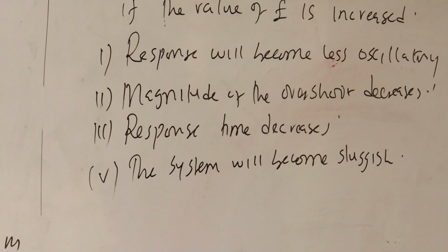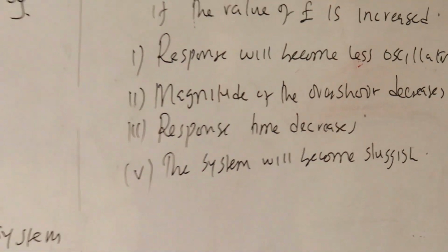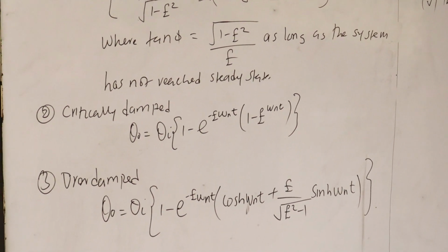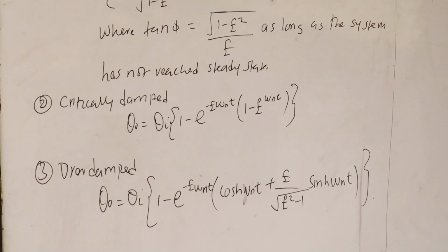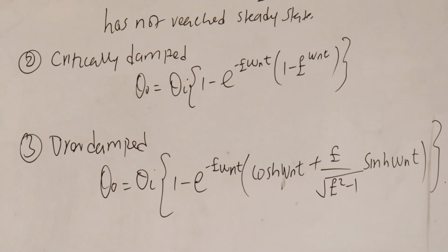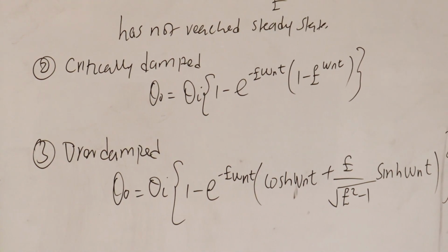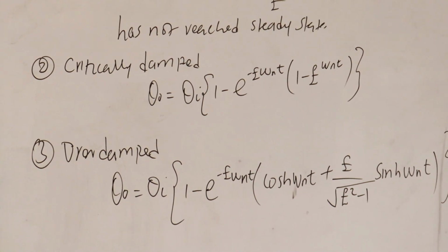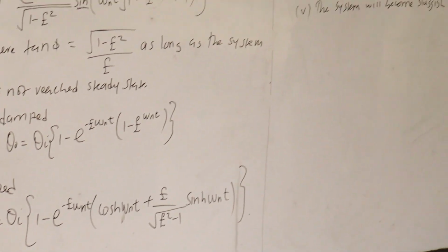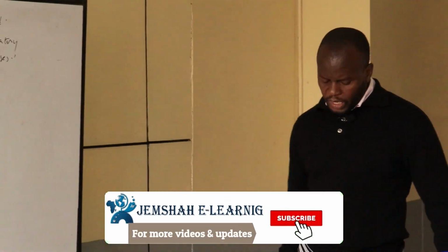So the response time can always be reduced by increasing the gain of the amplifier. This will increase omega n, and it will reduce the value of zeta. And if the value of zeta is reduced, then this may as well cause instability. Therefore, it is usually recommended that a damping ratio of between 0.6 and 0.7 is found to give a very fast response with the smallest overshoot.